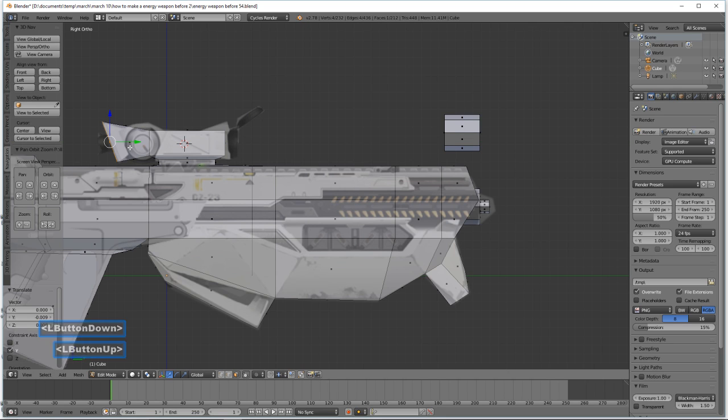I'm not concerned about this here right now. I'm just looking right here. The reason why I'm looking right here instead of there too is because I can just press A to deselect, hover here, hold control, and then while holding control, press R to put a loop cut in. I'll move like this, left click once, because I left click once, I can move this loop cut, move this here, left click to lock that in, and then press S to scale.